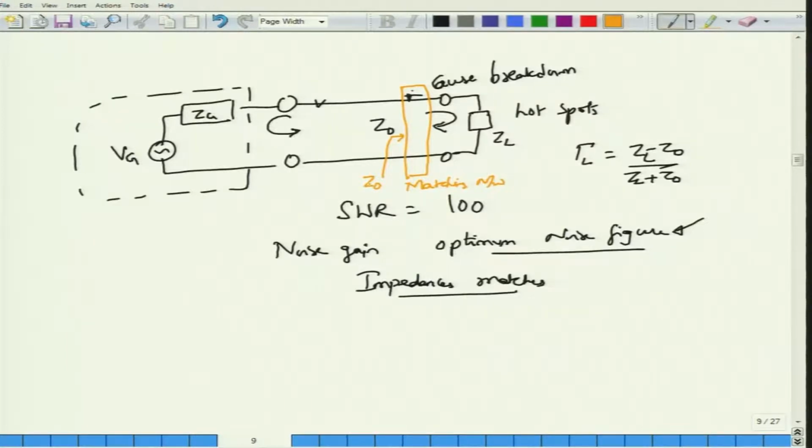So, what is the importance of this? When the transmission line encounters an impedance of Z0, clearly there will not be any reflections. Similarly, you put up one more matching network at the source end and look at the impedance seen there. Although the impedance to the left is Zg, after putting up a matching network your impedance seems to be equal to Z0. Again, when the waves reach the generator end, there will not be any reflection. So, you have actually eliminated reflections by performing what is called Z0 matching.